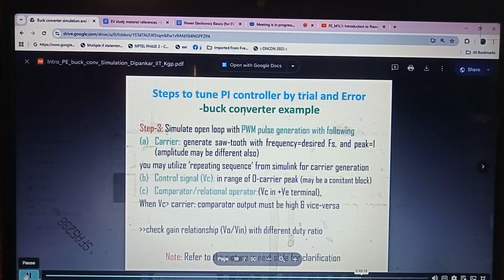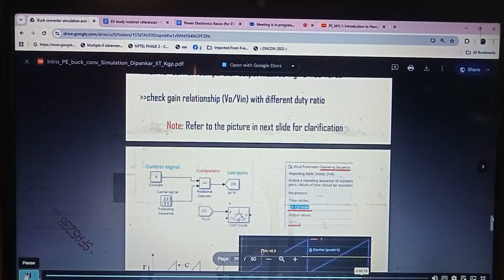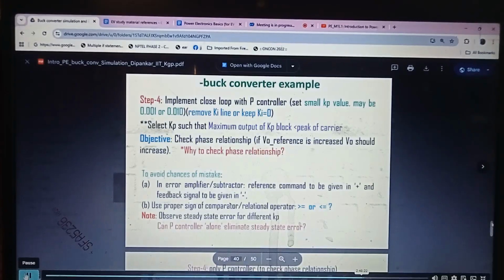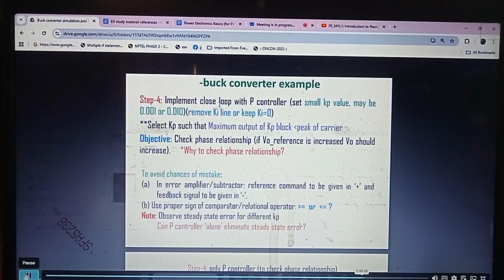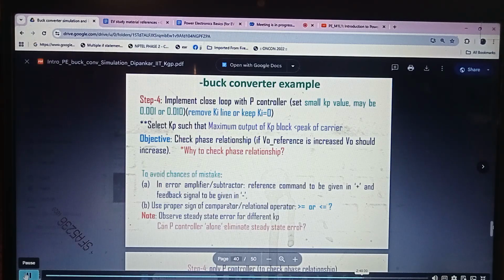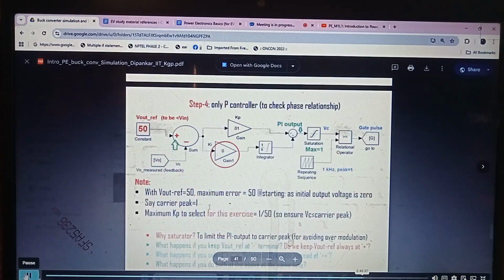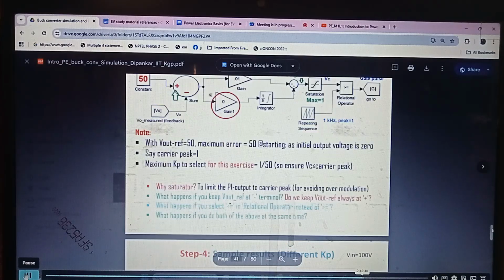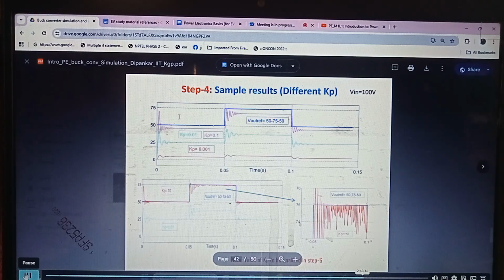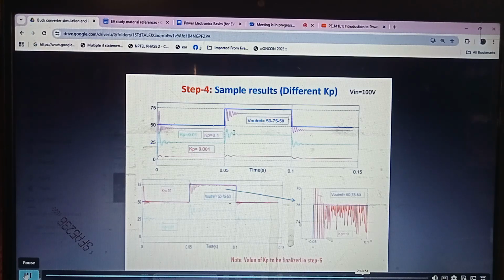So here you can see, I explain how easily you can set these KP, KI values without spending too much time. With this step by step, for example, generally we first do the P controller, then we tune the integral part, right? So where to stop, how to start, those things I have mentioned in detail. Of course, I cannot go line by line now. This will take a huge amount of time. So please go through them and see. I explain everything in very simple English with all those plots also, so that you get an idea. I gave you the simulation file. I gave you a step-by-step guideline. I gave you the result, what to expect. So what you have to do is spend time and follow all this. Hopefully you'll get it. Okay. First decide KP, then decide KI, then do both of them and tune it.